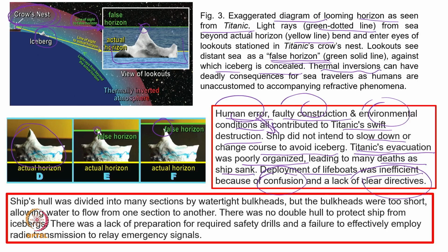Now, another thing I found, particularly about a ship hull, is that we keep in mind that if this kind of damage happens, the hull should be divided into many sections, the reason being that the surface area will increase and then there is a possibility of floating. However, they found that those sections were also not watertight. When water leaks into them, naturally the ship will sink. So they found there were some drawbacks in the design, and the bulkhead unit itself was not safe.